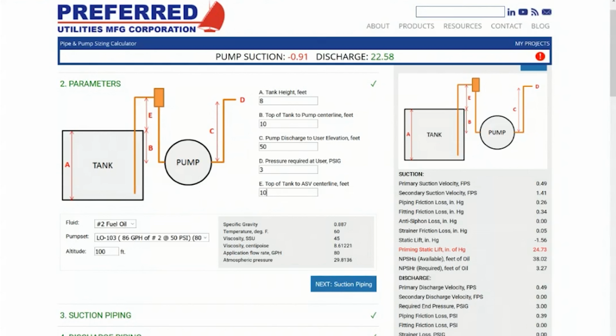Even though positive displacement pumps are described as self-priming, self-priming is kind of like walking distance. How much time do you have and how much wear do you want to put on these pumps when they're dry? They're going to wear at a much faster rate than if they were flooded with fuel and running happy. And in a pinch, I would also say that if you have a system in the field where you have an anti-siphon valve but you don't have a priming funnel, you can also make do by putting fuel into the anti-siphon valve, which should be installed at the highest point of the system.